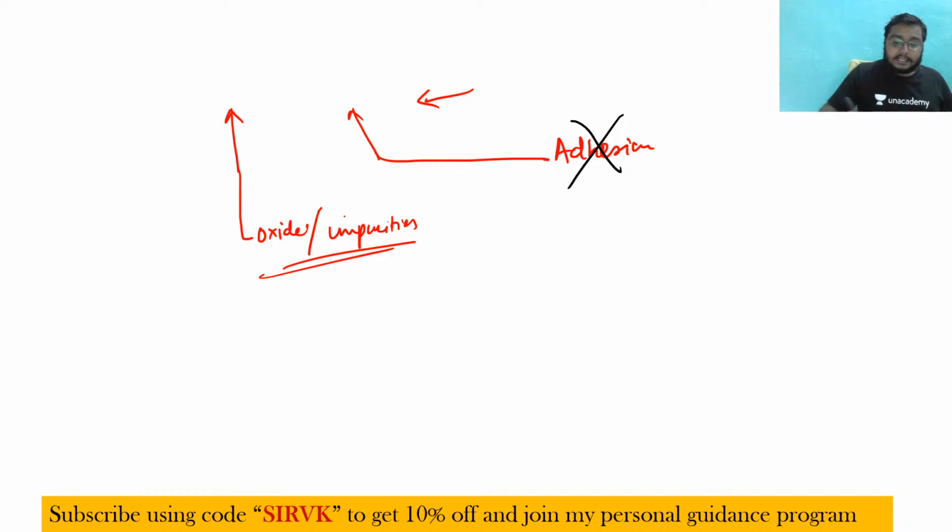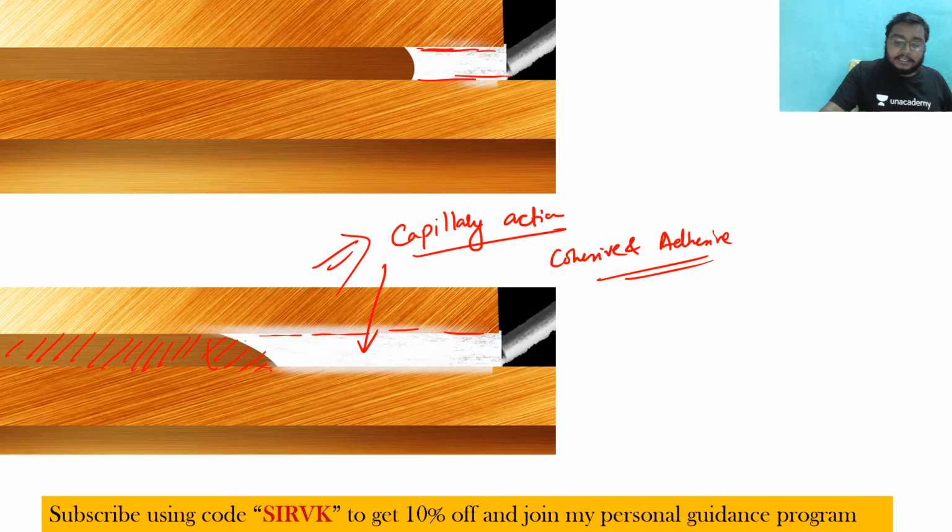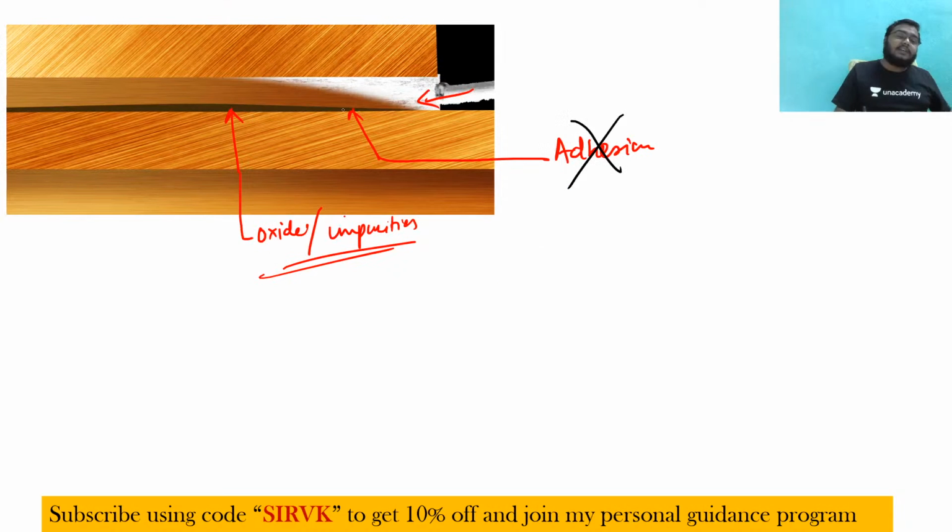See, in the earlier case, the surfaces were very clean, and hence the filler material was sticking with the other surface because the surface is clean. That's why adhesive force comes into play. But now here the surface is not very clean, and definitely adhesive force will not come into play, and hence we are not getting a good welding, not getting any welding.